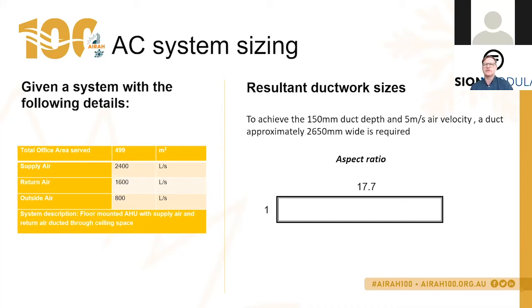Those low spots allow for a build-up of any moisture or dust or contaminants, and this could potentially cause a health risk. And it's also very difficult to install ductwork of this width. More than about 1500 in width starts to get rather difficult to install, just because of the physical limitations of a person trying to actually hang ductwork of that width and that size.